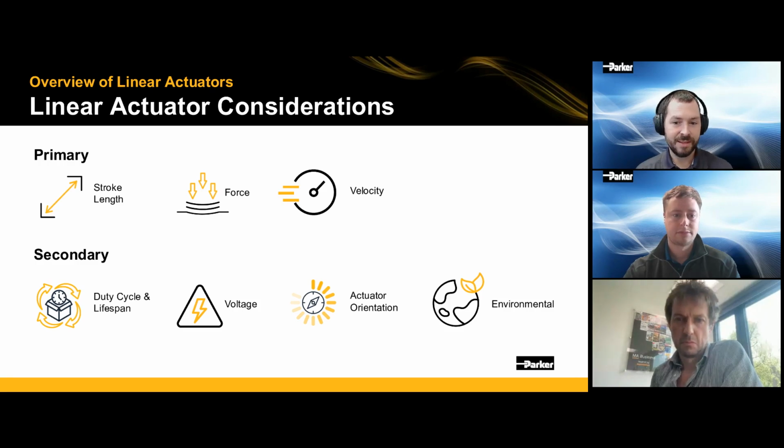Your mechanism likely is interfacing with some load, so there is some kinematic relationship between the distance and force. It is required to select an actuator that can transmit the amount of force both in extend and retract that your application needs.